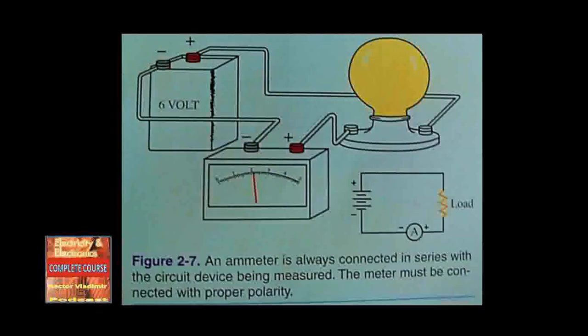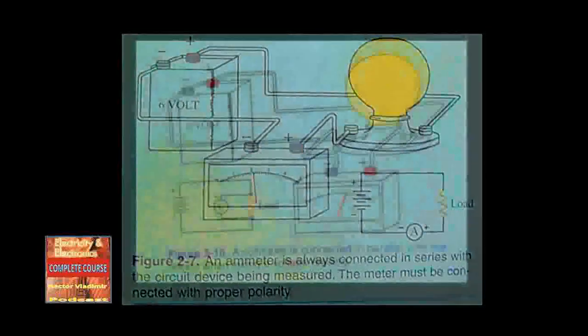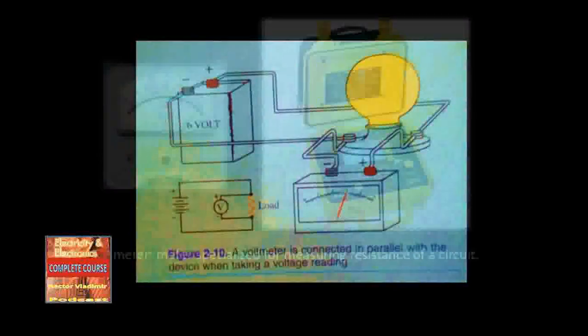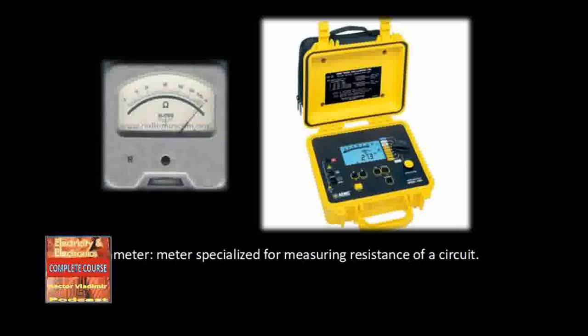How do you connect an ammeter to a circuit? In series, by first opening the circuit. How do you connect a voltmeter to a circuit? In parallel with the load. Which of the 3 meters should not be used while the circuit is energized? The ohm meter.